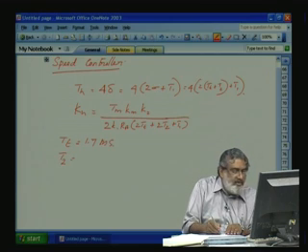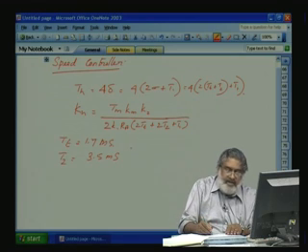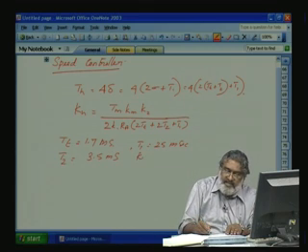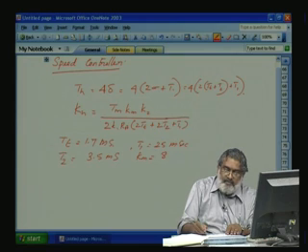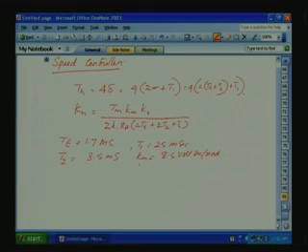Then T2 is equal to 3.5 millisecond. And T1 is equal to 25 milliseconds. This is all given, our filter smoothing time constant. And Km, that is machine constant, that is 8.5 volt second per radian. See, units you should match, very important. And K2 we know it, K2 is equal to 1 by 120 is equal to 0.0083. And Ra we know, Ra is equal to 0.02342.